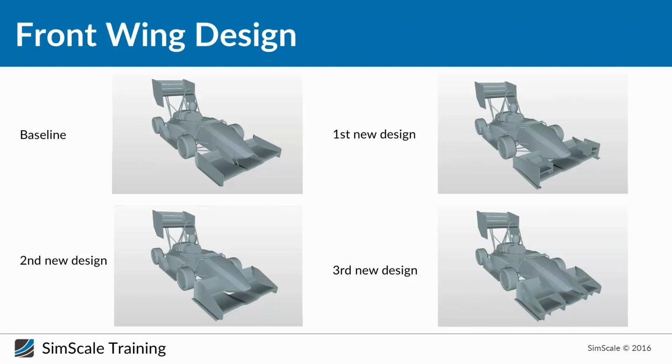I believe that cascade elements are more used for controlling the flow over the front tires, and from the results we have seen that the cascade elements can reduce the downforce that you generate with the front wing. Probably Nick can also comment on this: if the cascade elements really reduce the downforce created by the front wing, but you get more performance in terms of controlling the flow over the front tires.